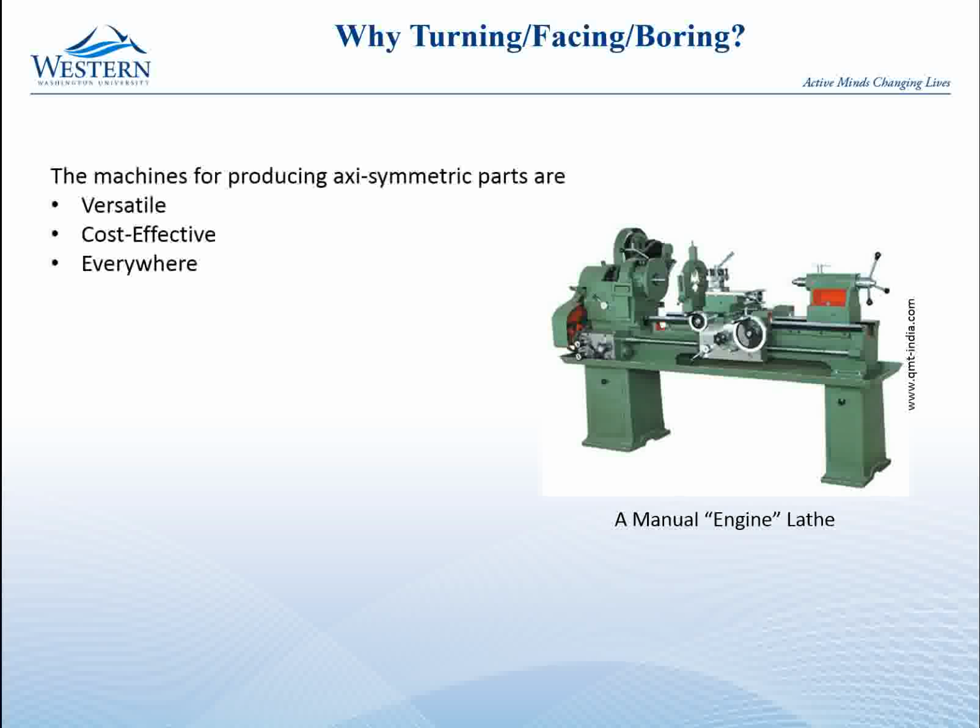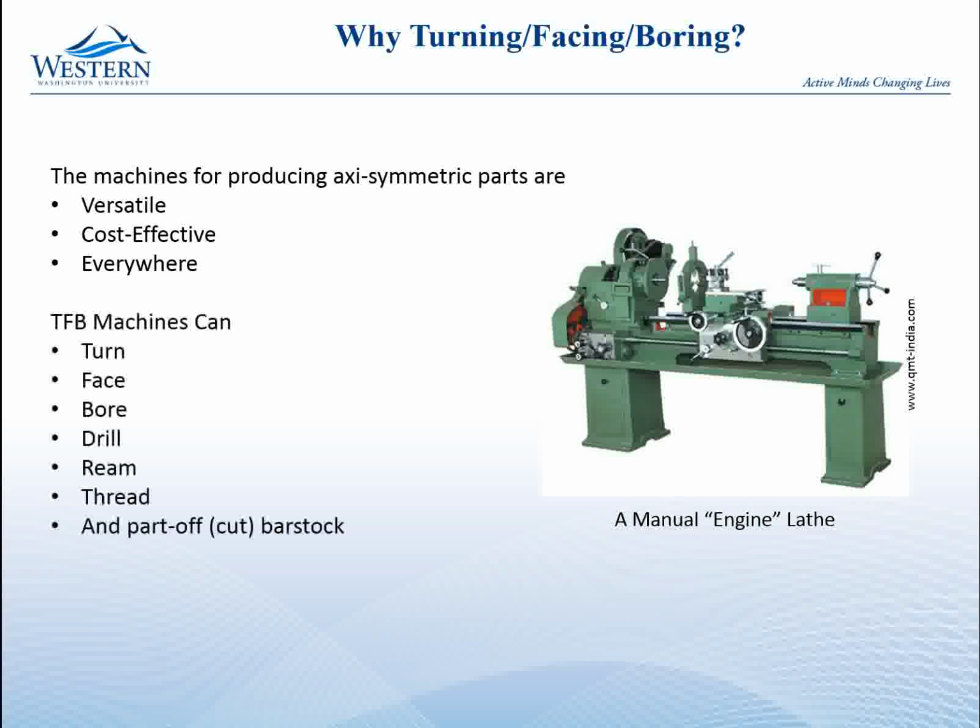So lathes are versatile, they're cost effective, they're everywhere, they're used a lot. You can do all sorts of things on them: turn, face, bore, drill, ream, thread, and cut off parts to length if they're axisymmetric. And so those are great things to be able to do. You can also do parts that are not axisymmetric and put axisymmetric features on them. So we do that sometimes as well.